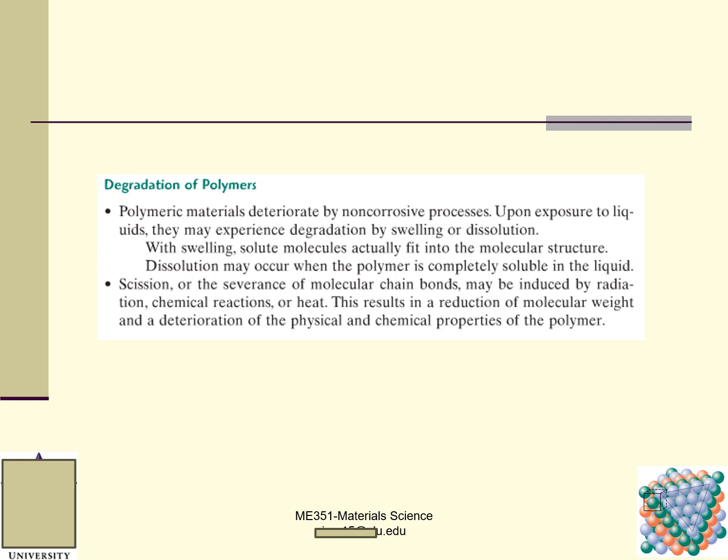It's different from what happens to metals and metal alloys. Upon exposure to liquids, they may experience degradation by swelling or dissolution. With swelling, solute molecules actually fit into the molecular structure. Dissolution may occur when the polymer is completely soluble in the liquid. Dissolution means it dissolves.